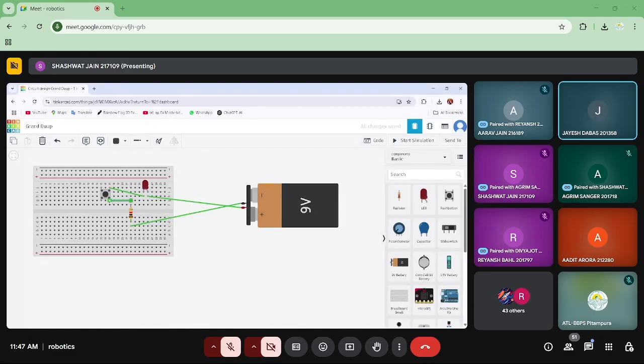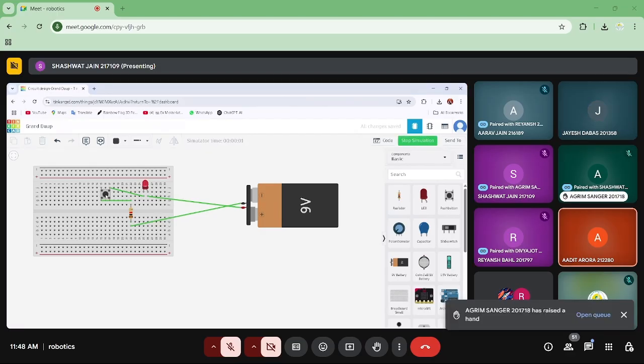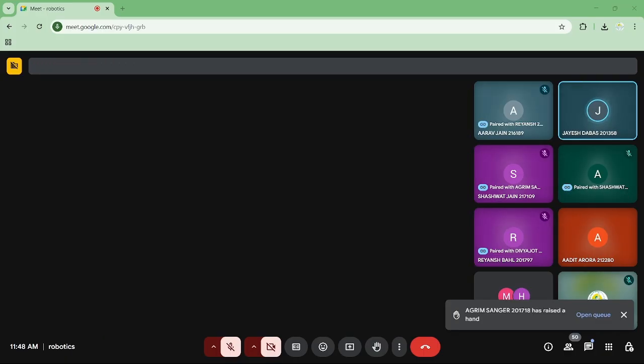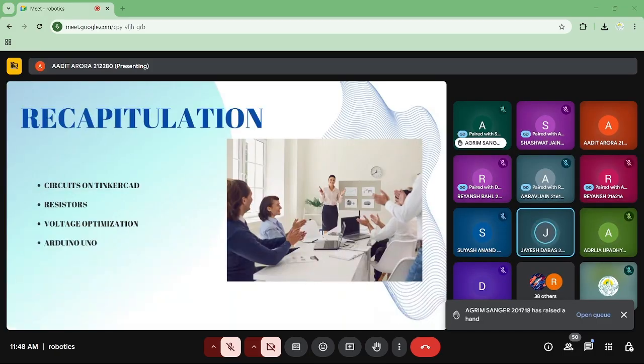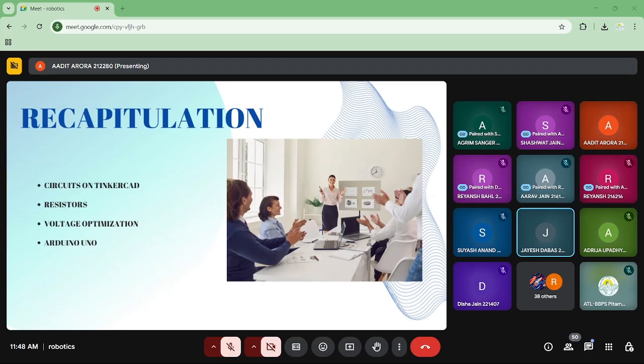Right. Now, when you run the circuit, it should work. See, perfect. So you just have to remember that in a push button, the vertical terminals, like the 2A and 2B terminals, are connected and terminal 1s are connected, no matter whether you're pushing the button or not. That's not the case for opposite terminals. All right, does that clear your doubt? Alright, so I think we're done with this.